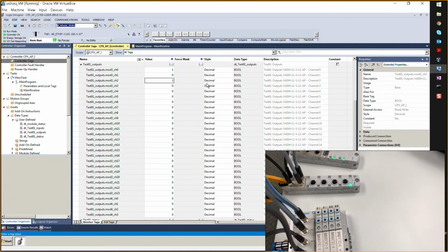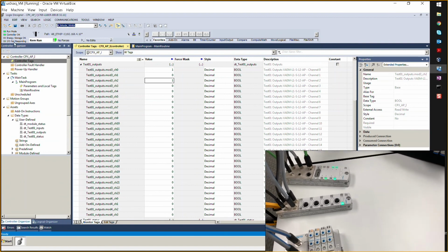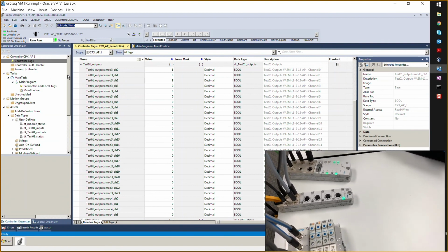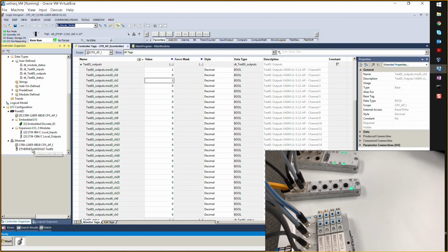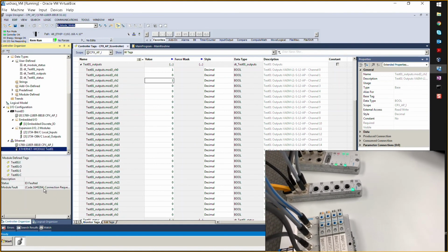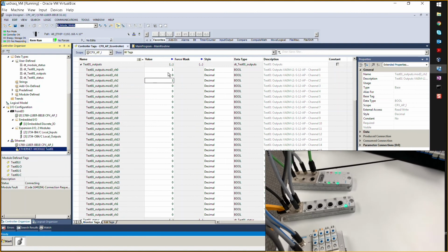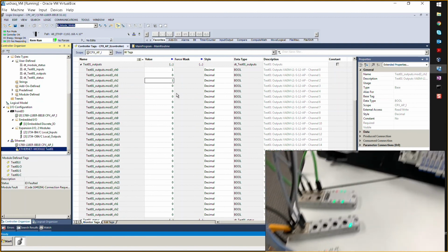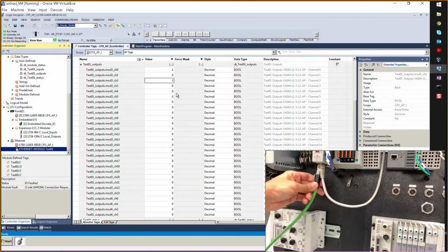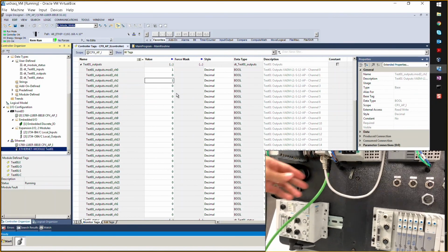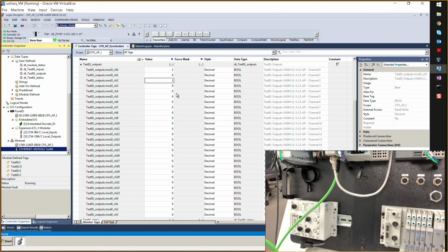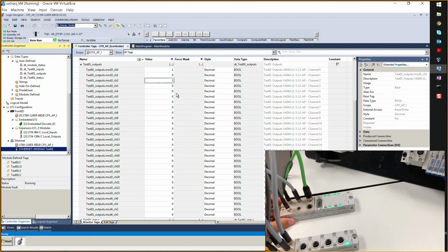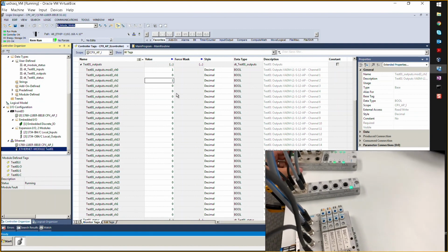So yeah, as you can see here, I/O not responding. These modules should say I/O faulted, right? Yes, which it does. Yep. But the valves, the coils remain on. Okay. I mean, yep. I see them physically here. Sure. And that's exactly how it should behave. And that's a parameter setting that you've created now. And this is the way to do parameterization with the AP system.